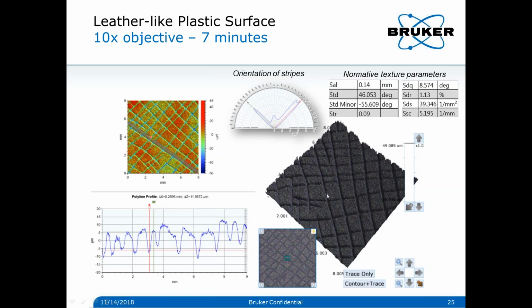You can also, and usually this is the case for matte and shiny surfaces, use the mean slope roughness, the Sdq, which tells us that we have a mean change of slope around 8.5 degrees. So the higher the slopes are, the more diffuse the surface is, and the more matte the surface is instead of being shiny.